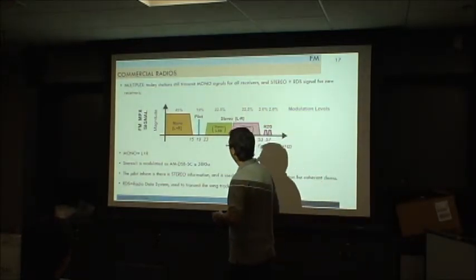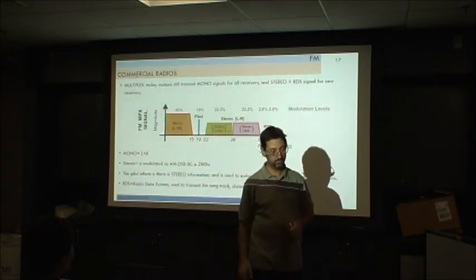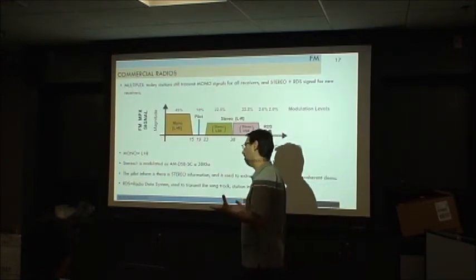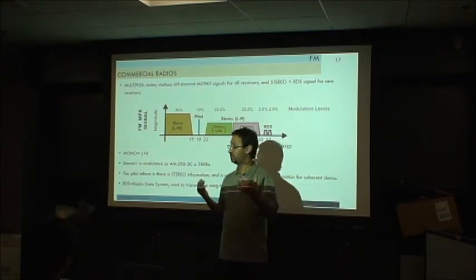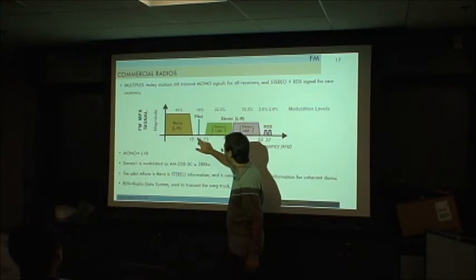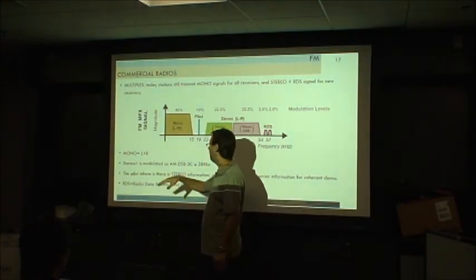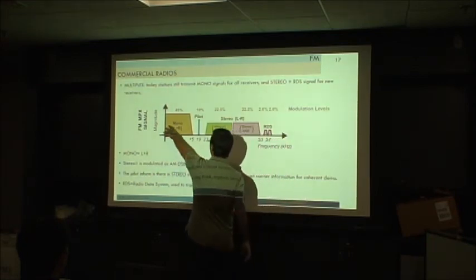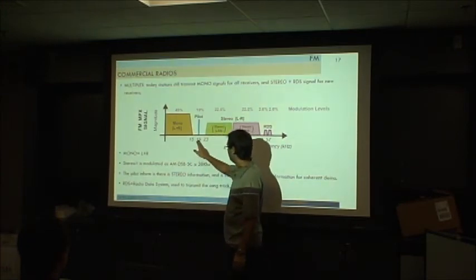And this is how actual FMs are. At the beginning it was just mono. Then when stereo came, these guys knew that the better and cheapest way to get the signal back is to have some tone there to recover it from. So that's why they are transmitting it. This is actual, so you will see how actual FM is working now, and you should see something like this. You should see some spectrum here on the mono, the tone. But take a look at this tone.